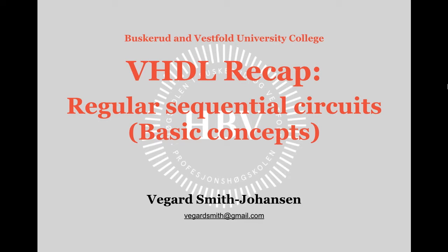Basically, a sequential circuit is a logical circuit that depends on both the present value of its input signals and on the past history of its inputs. The sequential circuit's outputs can depend on past history of inputs because it has a built-in memory. This makes us able to reuse the output as a different input if needed.